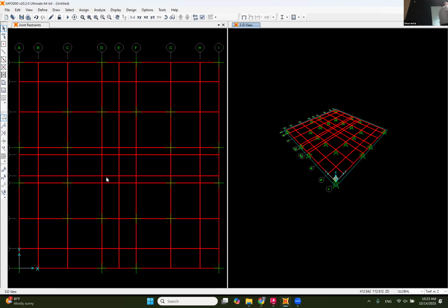The problem with the wall, if I want to model it, is that the column is just at one point, but the wall is linear. So what I'm gonna do is make a beam like here, and make this beam really, really stiff. Imagine with me that you have a wall here. If it's a column, the column is just holding at one point. But if it's a wall, it's holding the whole area. So this slab is feeling a very stiff element here, which is the wall.